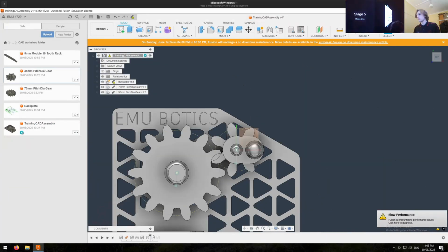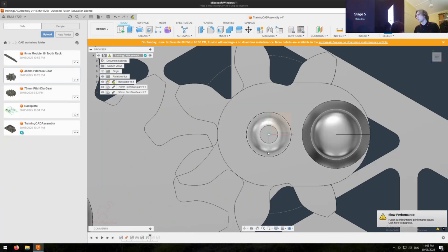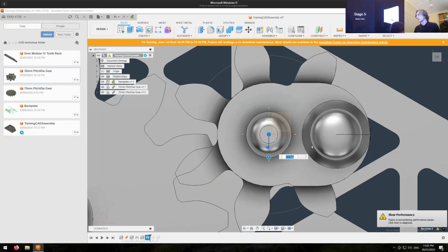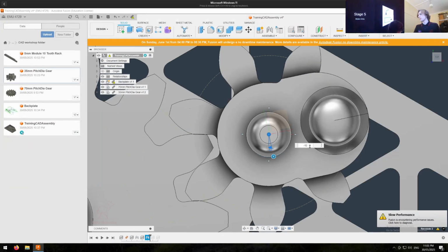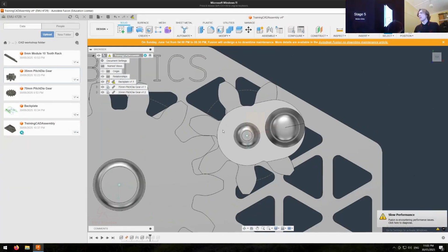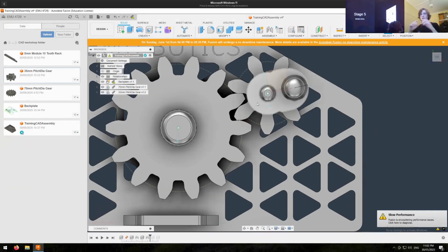is that we need to do it before our motion link. So I'm going to do what I just did. I'm going to rotate this until it's what, -11, and that made it work. No, -12. And then we're going to do our motion link when they're already meshing properly. So you need to sort out the meshing before you do your motion link.